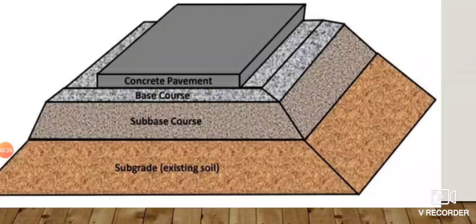If we are not providing any separate drainage layer, this acts as a drainage layer. That's why this GSB layer should be laid over full width of the prepared subgrade and extended up to the side drains.